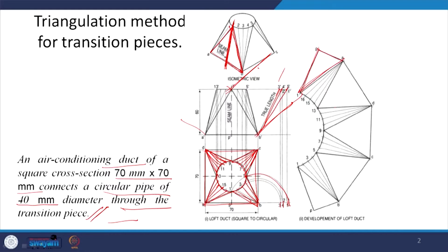Now, what we next have is this piece which is coming here. For this piece, if this cone was extended up, this apex point is what could have created a circular cone. So, this part of the sheet will actually be developed like a radial line development. So we will develop this. This is the part which is getting cut, and this is the rest of the part, and the circumference of this circle is going to come here.